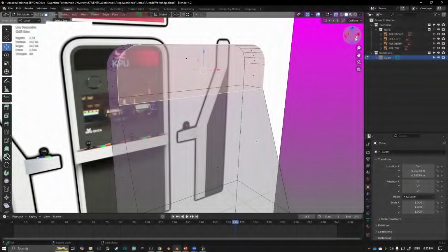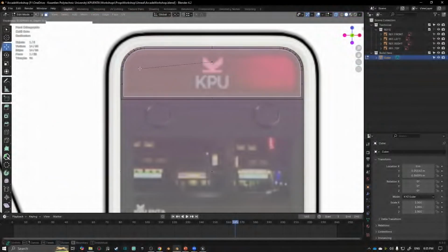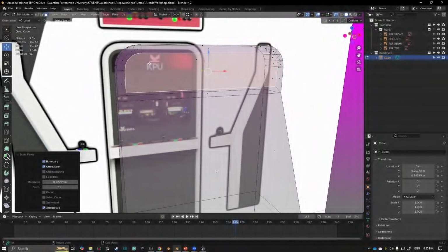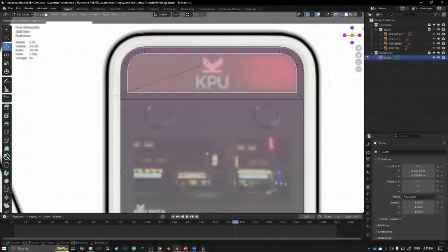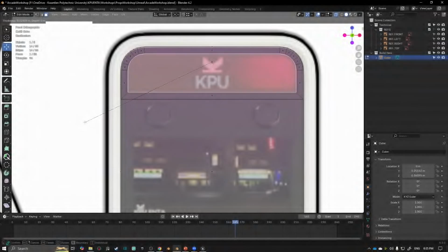It's very strange. Okay, so we've got this piece selected. We're in our front view. I'm going to hit I to inset. And I'm just going to scale this down, inset, inset, inset, until, yeah, definitely big Adobe energy. So I inset this in so that it kind of fits with our reference image. So number one rule of creating anything in 3D is work from reference. Unless you're a concept artist. If you're a concept artist, go ham, right? You can just do whatever you want and then just blame it on the fact that it's a concept. Okay, so I hit I and then just drag my mouse until it kind of lines up with the reference.